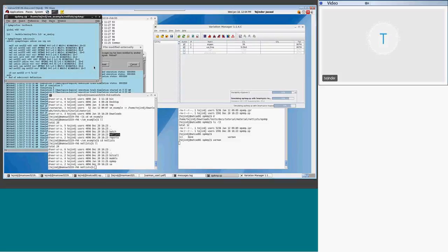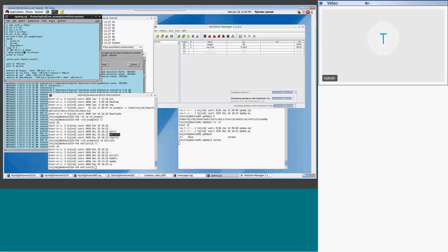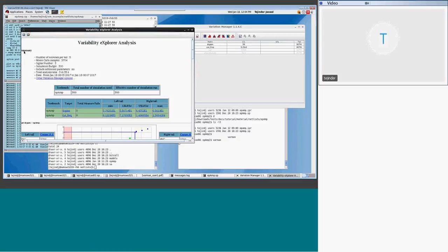If you look at SPICE Monte Carlo and variation, you can define those on the parameter, Gaussian or similar, with a percentage, and add that, and that will do the job too. If using something proprietary that doesn't have a statistical model, I'm not recommending it, because that's going to be a little bit more work.